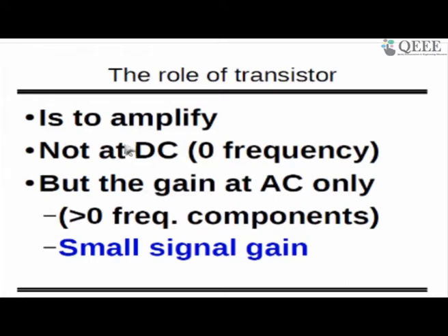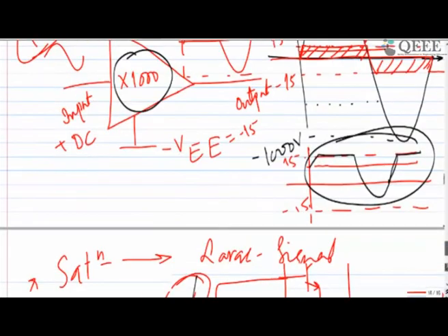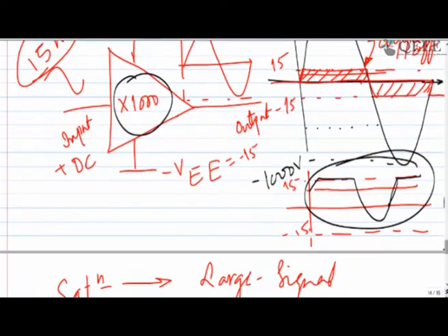The most important part is first to give the proper DC value, because now we understand that if we are not giving the proper DC value, or if there is unevenness in the DC value, your system will have some harmonics. If you have studied the Fourier transform, you must remember that if this side and this side are not equal, you will have different harmonics.